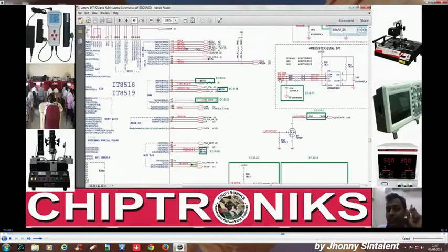And this chip select would also be provided by the IO controller. So during the powering on, we need to check two things: chip select and serial clock. We'll discuss the exact steps while checking the IO controller, whether my IO controller has initialized or not.